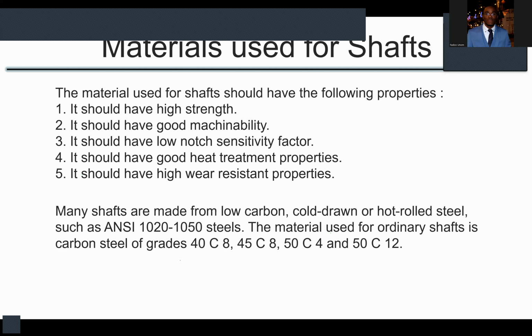Okay. The next property is wear resistance. Your material should have high wear resistance and high corrosion resistance, because you will need lubrication. You will need lubrication to allow for, one, heat management, and two, to reduce wear as the machine elements or gears are touching each other, constantly engaging and disengaging.